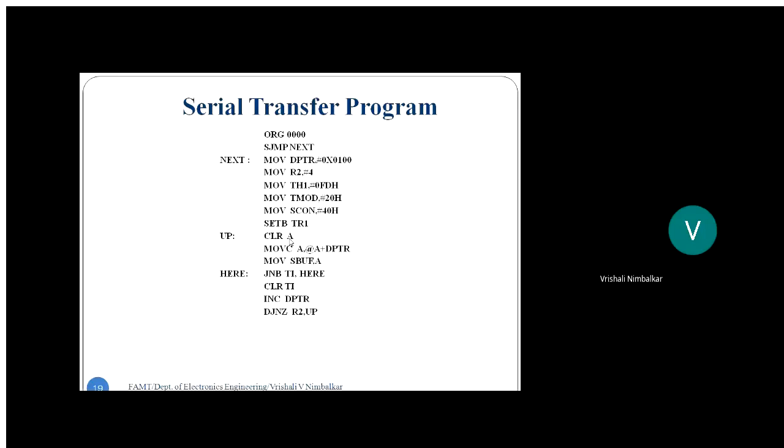Take the second character in the accumulator. Taking the character is done by MOVC A, @A+DPTR. So before using the accumulator, clear it, or else there is some random data in the accumulator. In fact, the ASCII code is what is there currently, and that will get added to the address. No, I do not want that, because DPTR is pointing to the correct address.